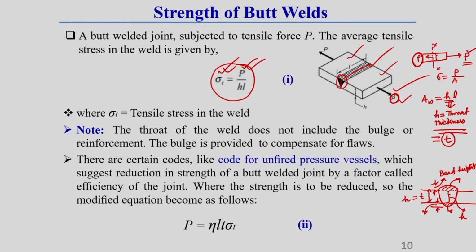That is why I have written here that the throat of the weld does not include bulge or reinforcement, that is, the top bead height or top reinforcement portion.